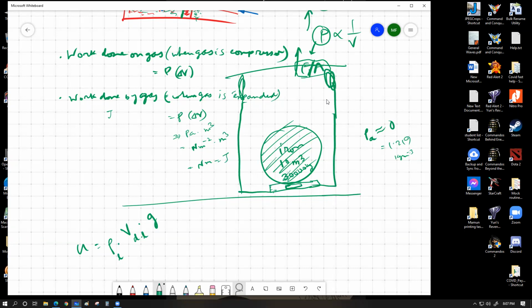But whenever we slowly start to drop it, we're going to see that the weight value slowly decreases, because the downward weight is going to be constant, that is 30,000 into 9.81. But as we slowly submerge the sphere downwards, it's going to experience an increased amount of upward force because of the upthrust. And when the entire thing is underwater, it's going to have the maximum upthrust force, which is going to be 10 meter cube into 1000 into 9.81. So 1000 is the density of water, 10 is its volume, 9.81 is g.